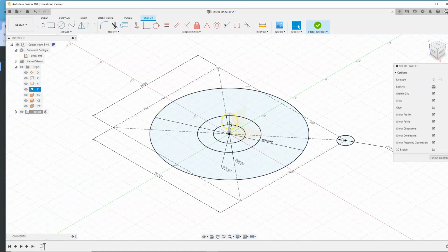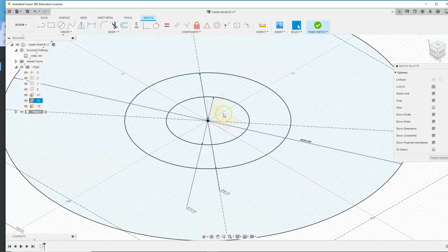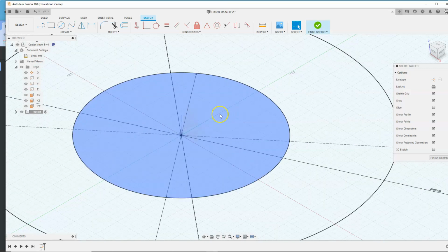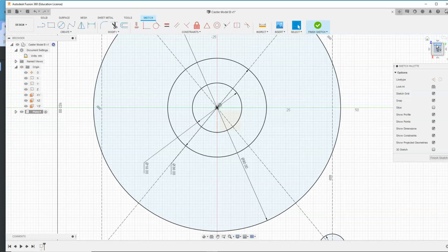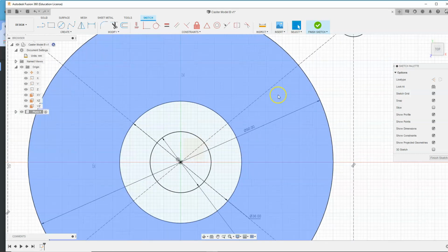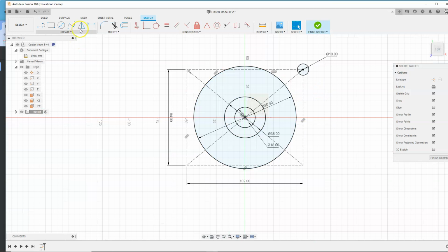Go ahead and change the view. Okay, so sorry, they're there. This is the Z-axis. There is the X-axis. And it's being kind of difficult and not letting me select the Y-axis. If you left click and hold over an area, it'll select all the things in that region and let you select those. So it's there. They're just very light and transparent and kind of hard to see. So I'm going to go back to my view cube, click on the top. Oops, and rotate it back around the way I want it. We're going to open up that mirror command again.